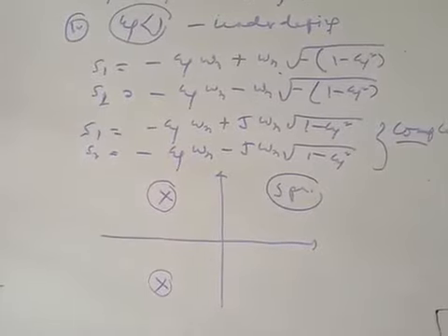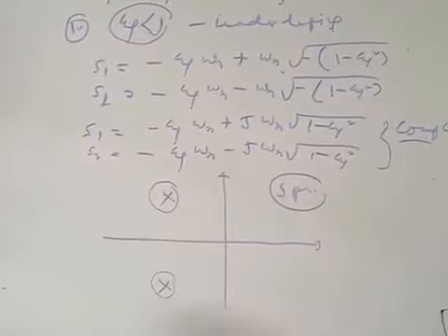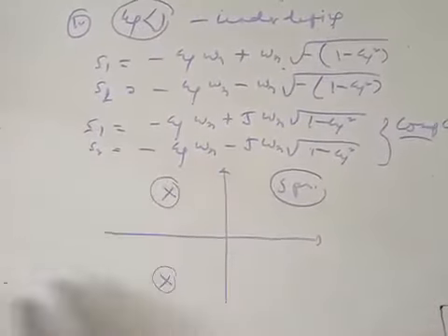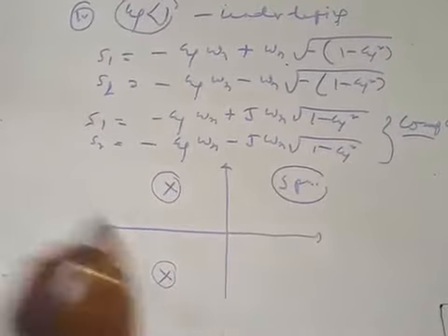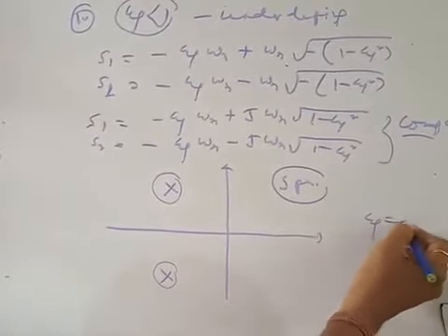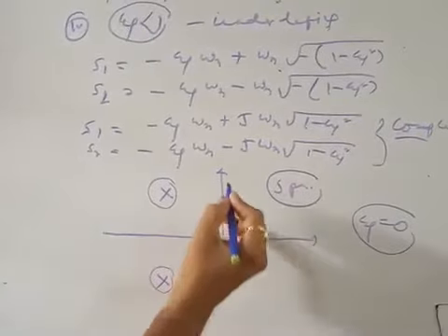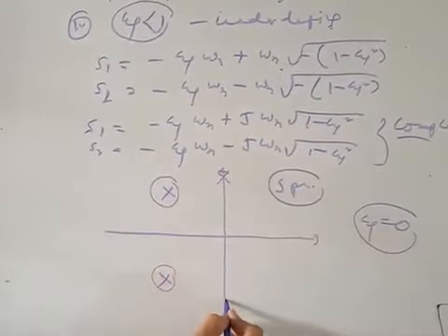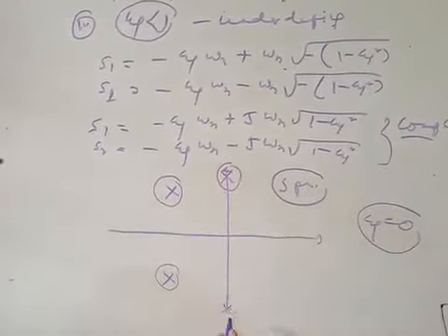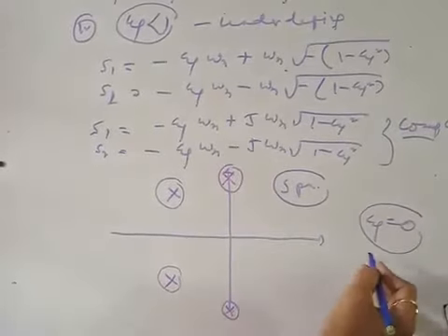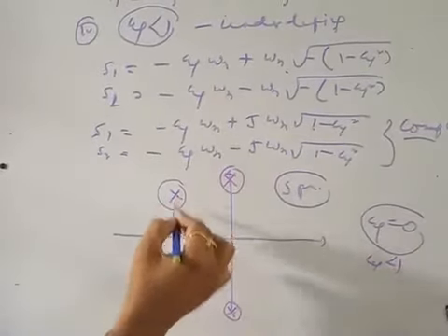And you see, for a system to be stable, the poles located on the left hand side of the S plane are stable. When the value of xi is equal to 0, the poles were located in these positions, and when xi is less than 1, the poles are located here.